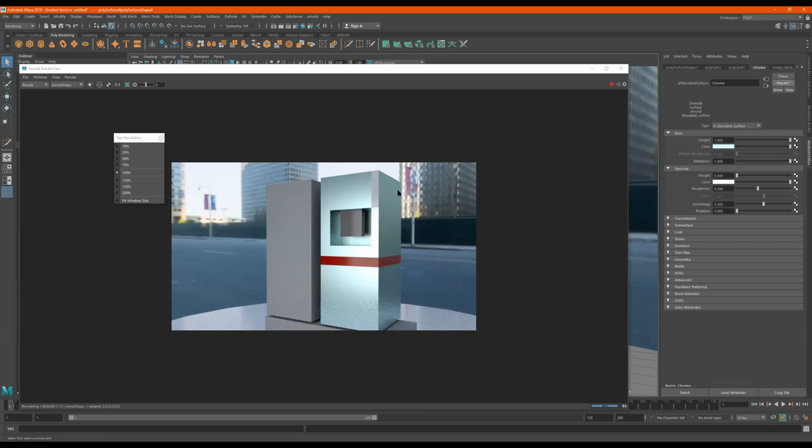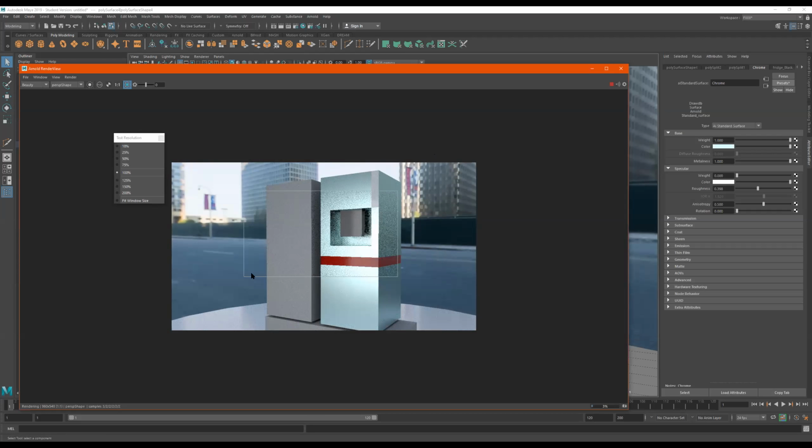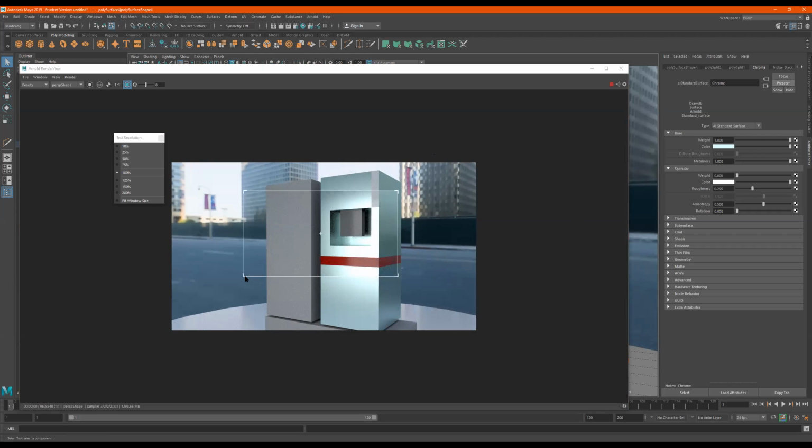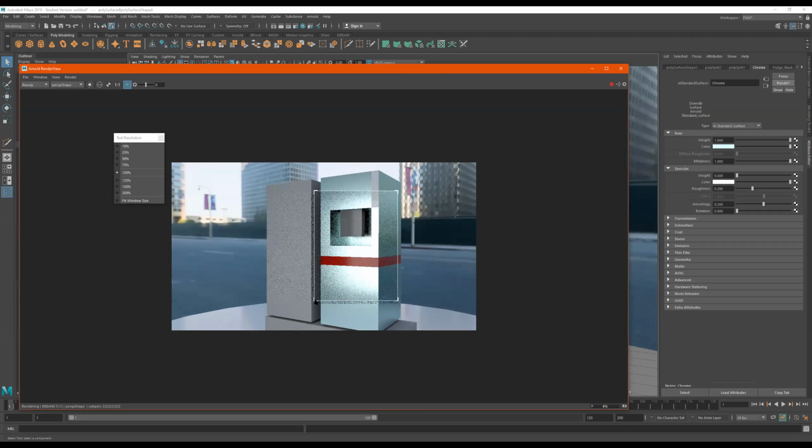So once again, to get this small preview window: shift, left click, draw the window, click on it, do the updates. And then you can also move this to get it where you want if you don't get it right the first time. So I can be like, man, I just really want to focus on this, just move this here. And the smaller this window is, the faster my computer moves, the quicker the feedback, the happier we all are. I hope that answered the question. It did. Thank you.